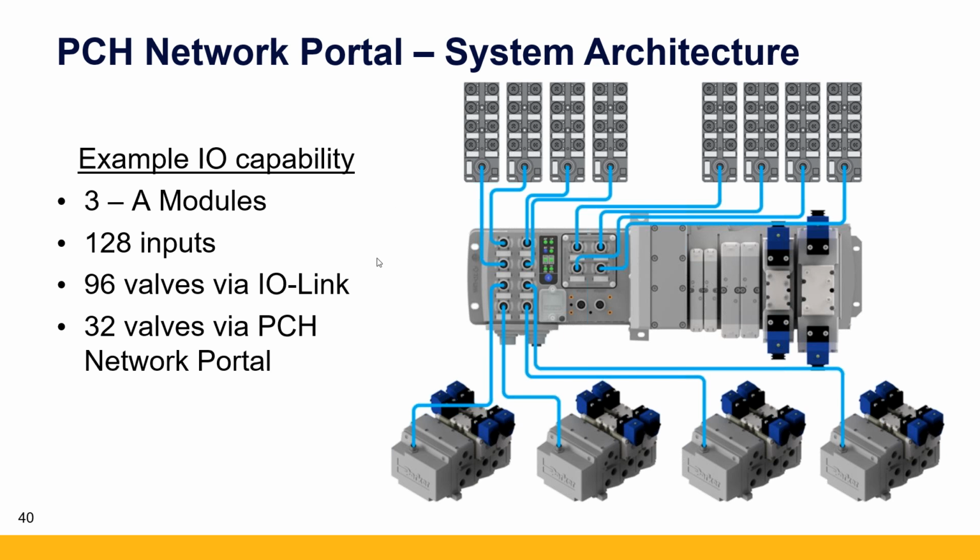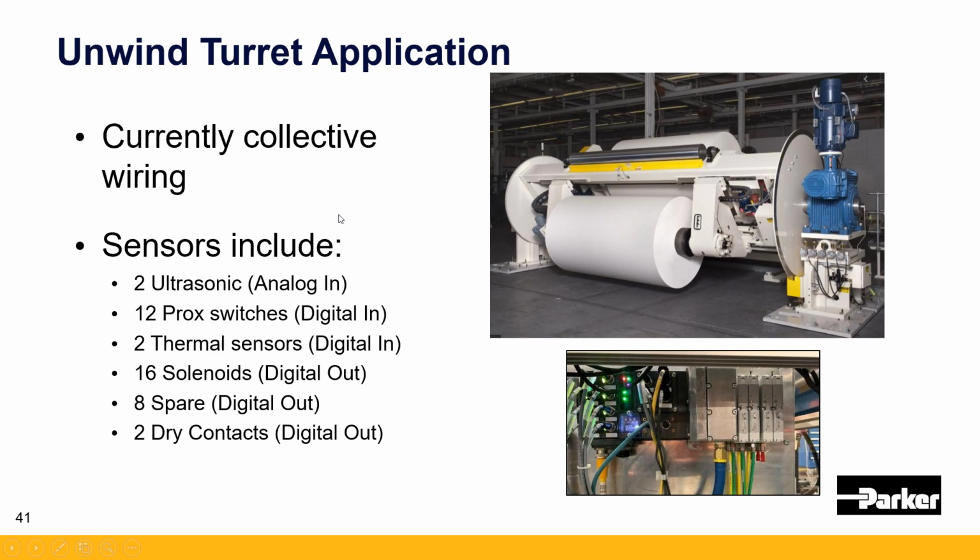We're seeing a lot of turnover and new folks entering the controls profession. We want to give them tools to help them do their jobs better. So it'll tell you, hey, you lost your auxiliary voltage. Maybe go power cycle something, eliminate a noise source, replace the device. We've catered all of these remarks to help you do that job a little bit better. And again, this is time-stamped and rolling, so you get 40 warnings, 40 errors, and 40 events.